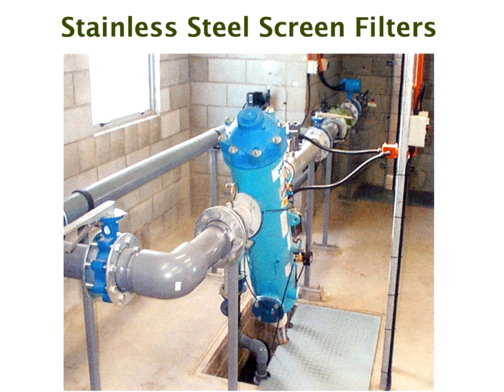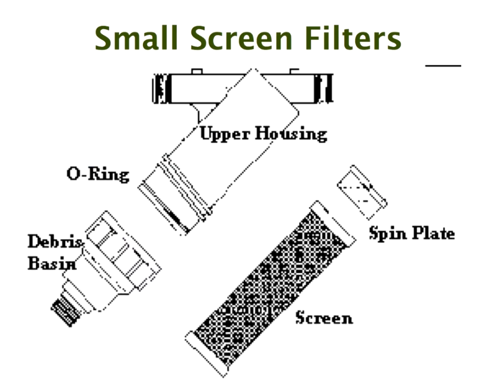Here's another filter of the same type, which is also a screen filter with a rotating self-cleaning, automatic cleaning filter. And this one's a little easier to take apart, but as you can see, the bolts around the top, and you have to pull it apart. On a really large system, people are prepared to do the maintenance, or have to do the maintenance. They have maintenance of the whole system anyway, so it's not too serious. So again, these filters work. I don't want to be negative about them at all. You've got to pick the right one for the right job.